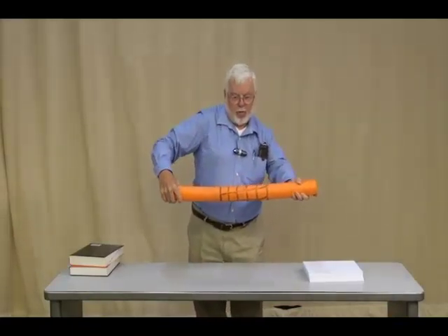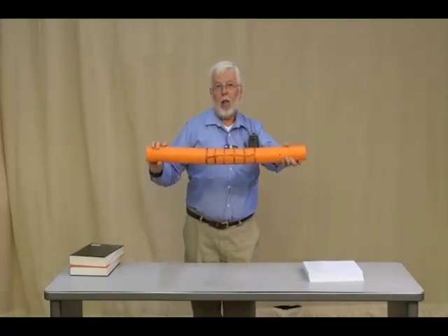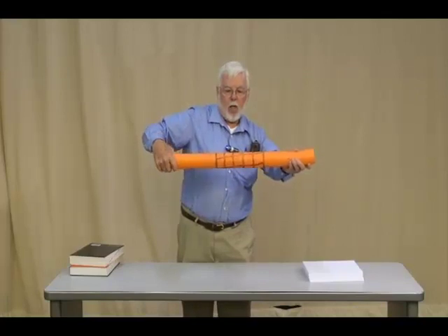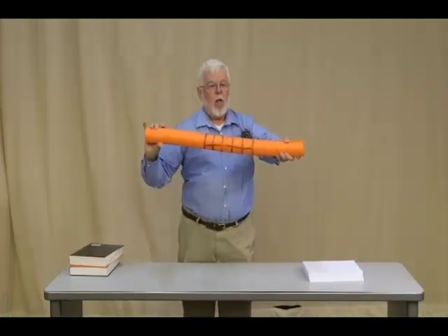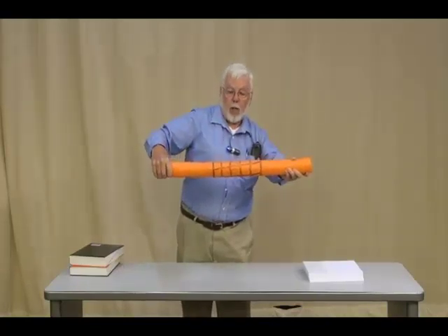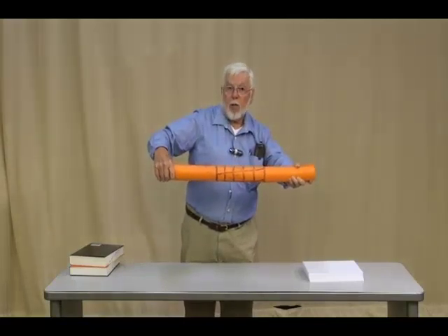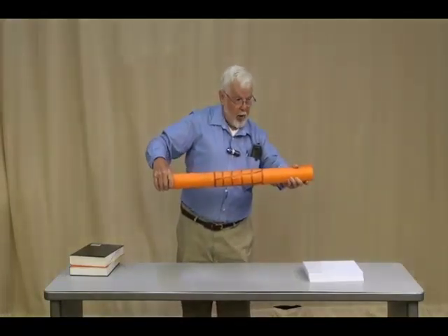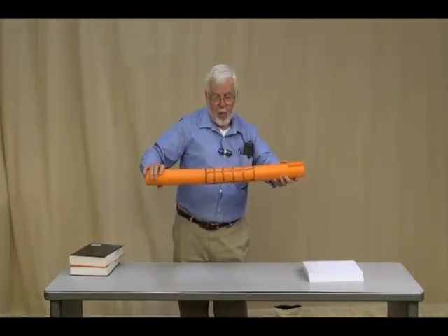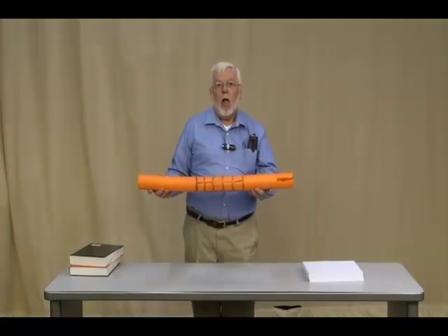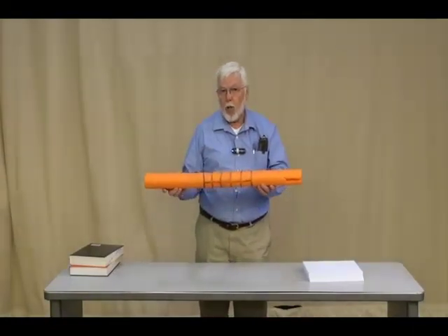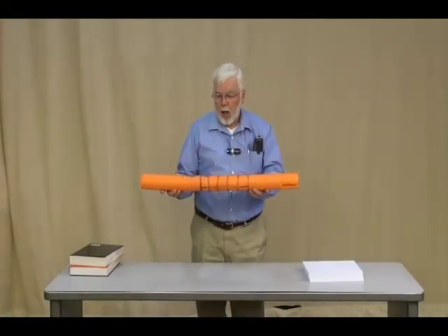And I want you to observe what's happening to the straight lines along the elements of this cylinder as I twist that in torque. Notice that they are changing angle, and that's indicative of the fact that I have torsional shear stress being developed in this noodle as a result of my torque being applied on the ends. Torque is a twisting force, as is a bending moment, but we call them by different names because their calculation equations are quite different, and it serves as an alert to the mechanical engineer as to which set of equations he needs in either case.